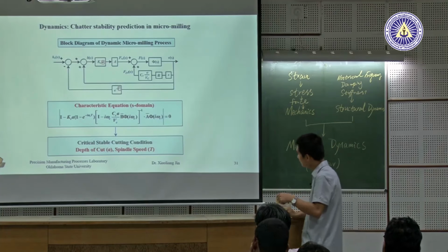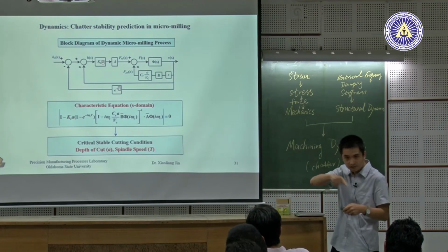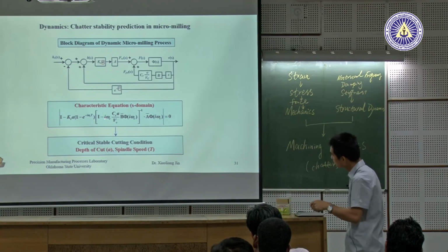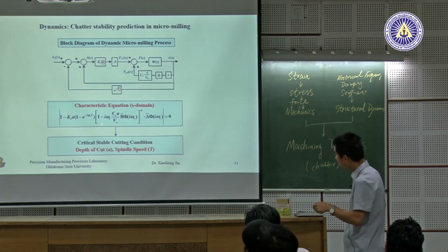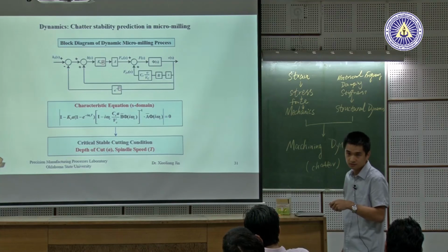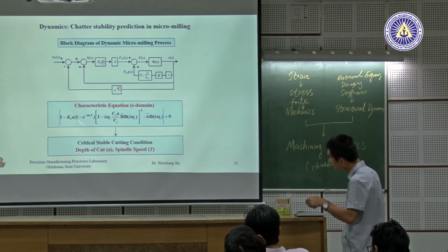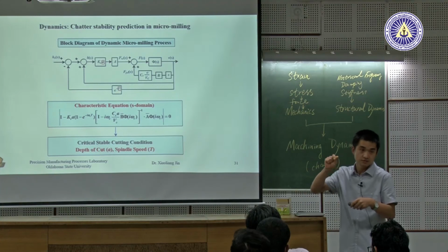So how I did it is, I first assume there's no damping and get the conventional stability lobe for the original case. Then, based on each spin speed, I assign a velocity, right? Then I go back and solve again, because if you know V C, it's just a constant. Based on that, I update the axial depth of cut.